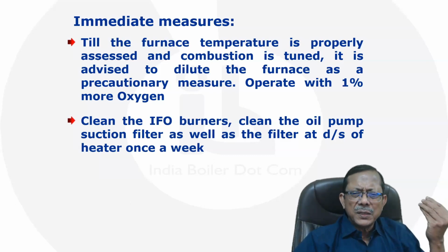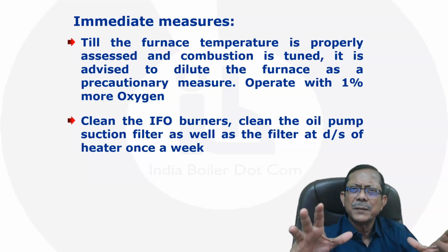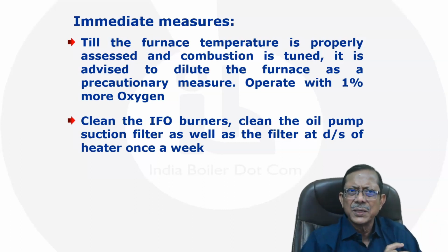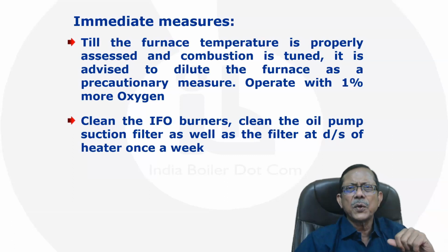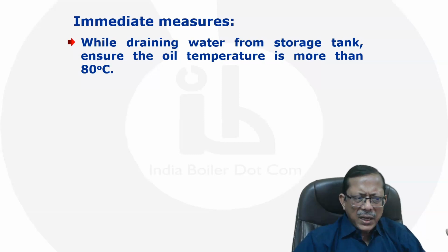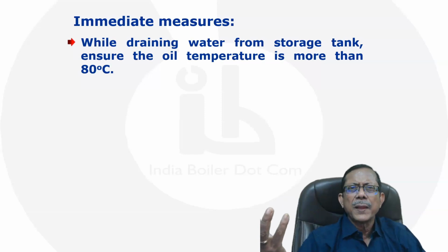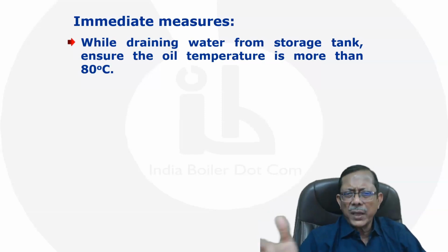Cleaning the IFO burner and cleaning the oil pump suction filters, because these are all factors which are responsible for the flame pattern, and they were not following the right practice. So burner cleaning and filter cleaning at least once in a week is always a good practice, and I have suggested that to them to maintain proper flame health. While draining the water, because they did not have a day tank, they were draining from the main storage tank, which was not being cleaned. Cleaning is immediately not possible, but draining has to be done